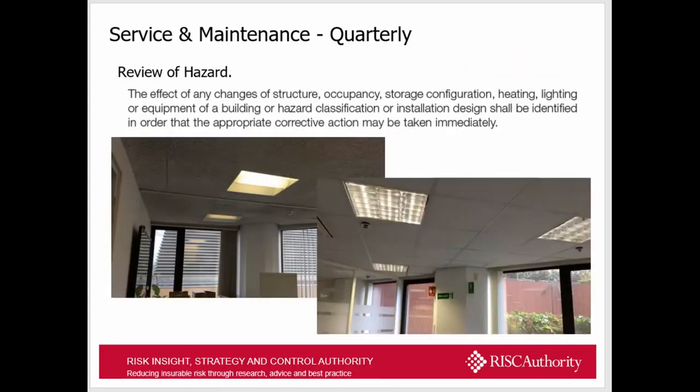The review of hazard. This is a quarterly requirement in both the British Standard and the LPC Technical Bulletin TB203, and this is the discipline that's most infrequently carried out and missing from most service and maintenance schedules, but one of the most important. This particular requirement is a review of any changes of structure, occupancy, storage configuration, change of heating, lighting, equipment, the classification of the building.